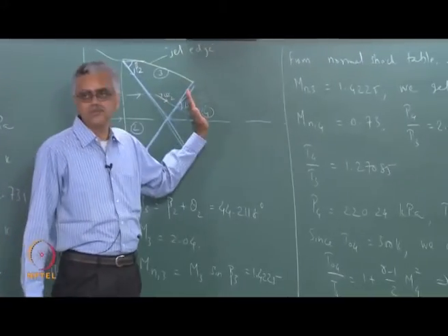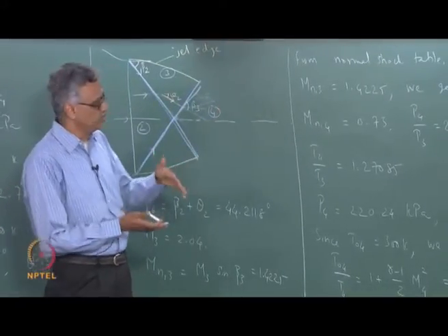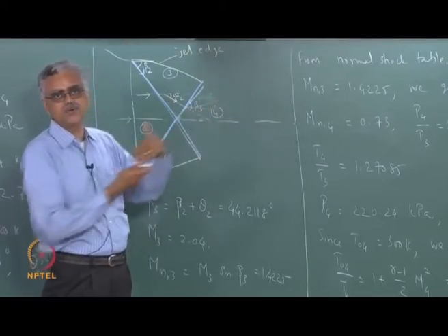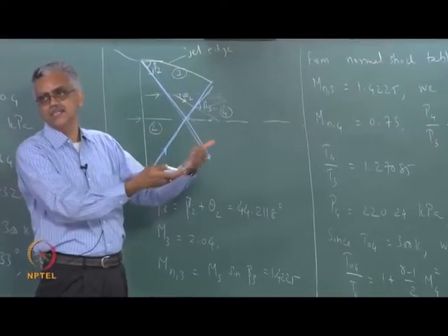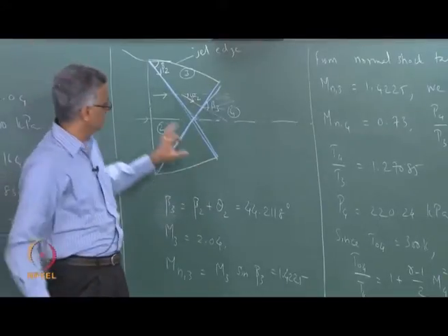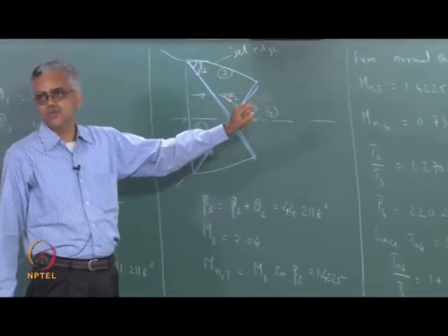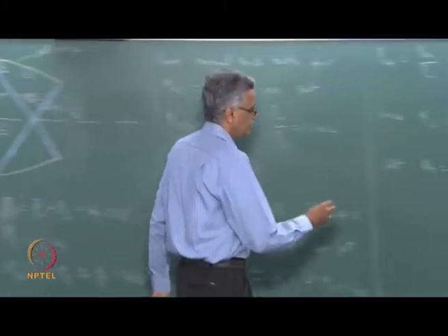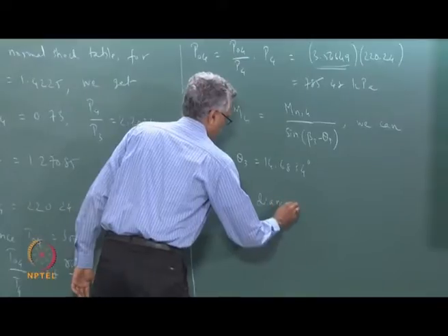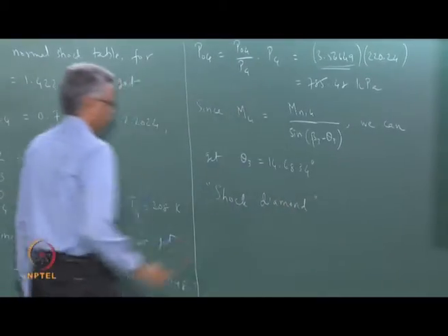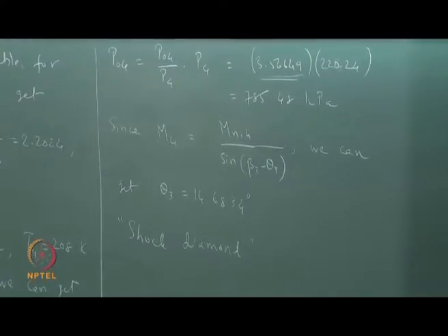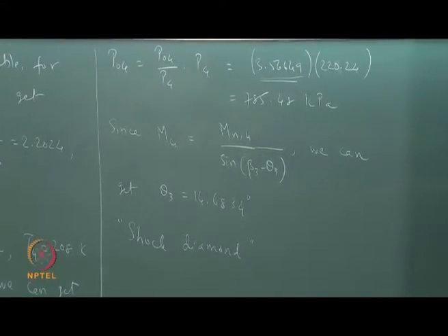We will continue the solution once more to see. But what happens is, you get this alternate compression, expansion, compression, expansion for a few nozzle diameters or exit diameters, and then eventually the jet becomes equilibrated with the atmosphere. In fact, this alternate compression expansion is usually called a shock diamond, and I will show pictures of this shock diamond later on. So you get these alternating shock waves and expansion fans and so on for several nozzle exit diameters.